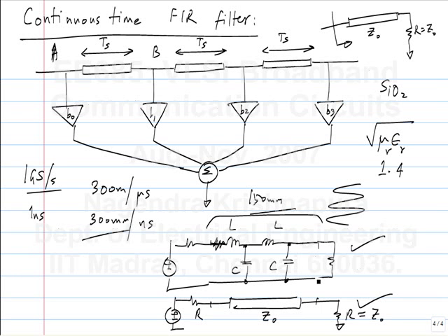And one more problem is that, for instance, you had the transmitter equalizer implementation. What happens if you change the clock rate? Will the equalizer response be the same? So you had a certain implementation of the transmitter equalizer. That is, you have D flip-flops and transconductors. You add the outputs of the D flip-flops together.